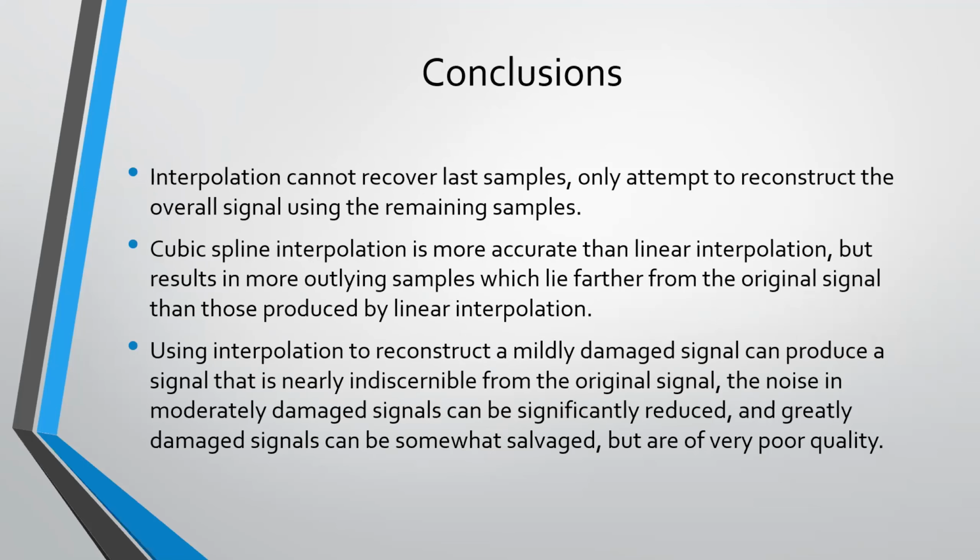In conclusion, interpolation cannot recover lost samples, only attempt to reconstruct the overall signal using the remaining samples. Cubic spline interpolation is more accurate than linear interpolation, but results in more outlying samples which lie farther from the original signal than those produced by linear interpolation.